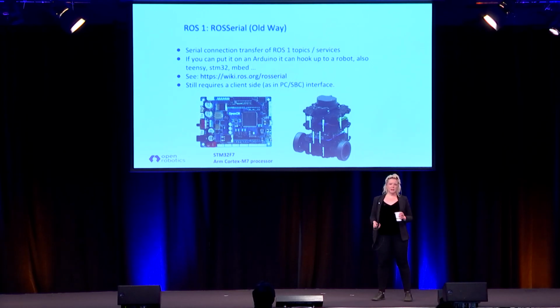The way this usually works is that people use a tool called ROS Serial. What ROS Serial allows you to do is take something like the OpenCR or an Arduino, set up your sensors, set up your actuators, and create an interface to a ROS topic. You basically have to have a sender and a receiver on your main processor to handle this, but you can learn all about this at ROS Serial on the wiki.